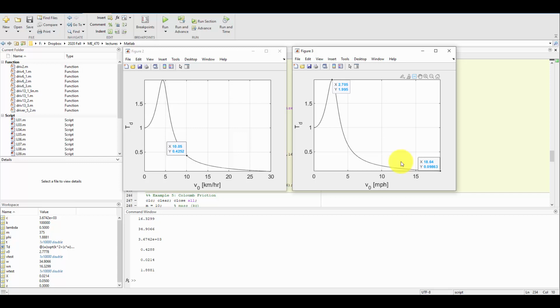Another caveat before you go attempt this in your own car over a washboard road is that we are treating this as a quarter car model. So we're saying that the entire vehicle only has vertical displacement. But in an actual vehicle, we definitely would have to be worried about the pitch of the vehicle and possibly the roll. Now, the roll may not be a big deal if the washboard road is sufficiently wide. However, we're making the assumption that the entire car is going to have the same vertical displacement, and that's not going to be the case. So we would want to go into probably at least a 2 degree of freedom model over the same system before we make that decision.